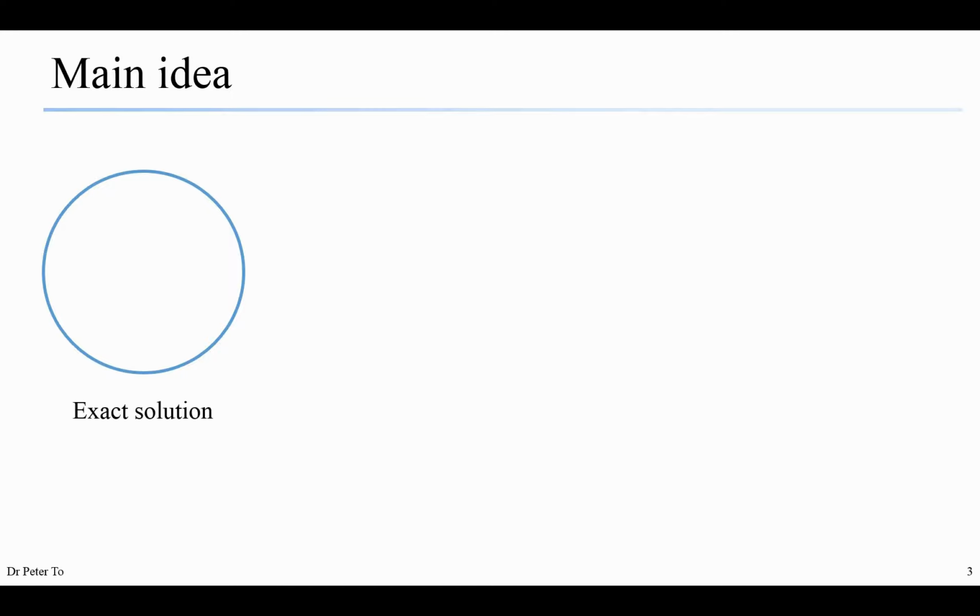There are 6 steps for the modeling preparations. In the first step, we have to do the symmetry reductions. That means if your structure is symmetric, you can just cut off the symmetric part and replace the interactions with some roller support or something like that. Or if it is uniform in one direction, you can cut off a dimension.